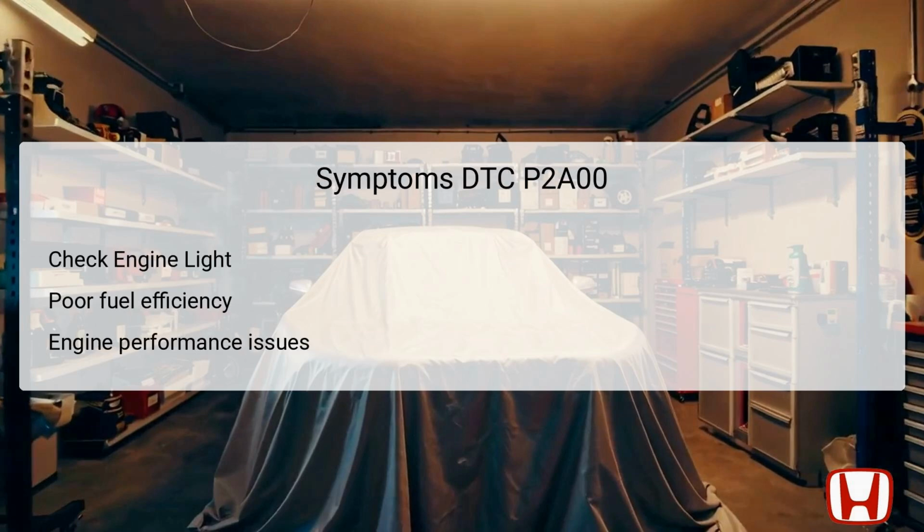Another potential reason could be errors in PCM processing, where the module does not accurately interpret the data received from the sensor. Environmental factors, such as exhaust leaks or intake manifold leaks, could also affect the sensor's performance. Thoroughly diagnosing these potential causes is essential for identifying the root problem and ensuring proper repairs are made to restore functionality. When DTC P2A00 is triggered, drivers may experience several noticeable symptoms.